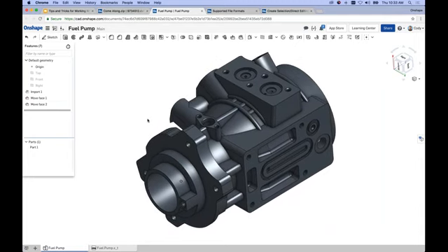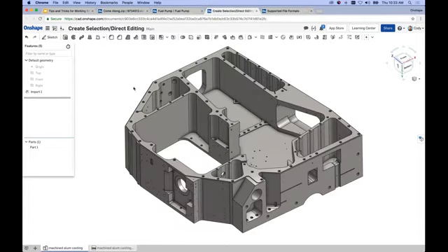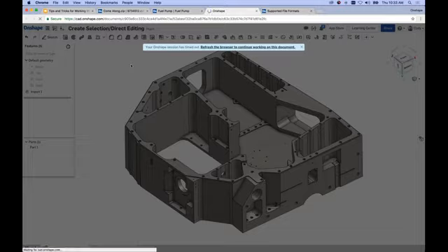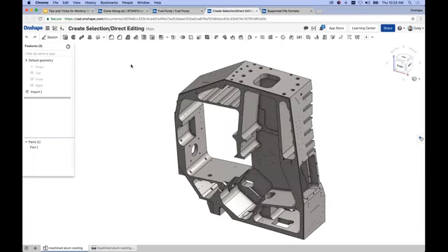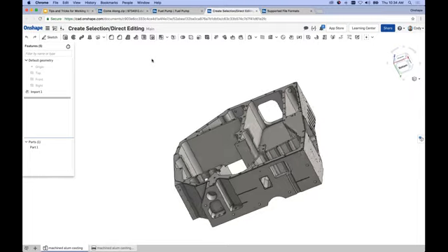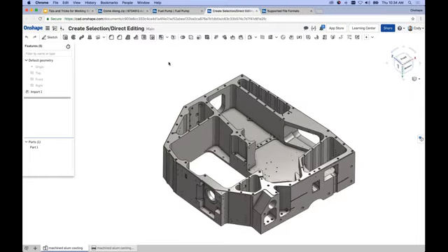So the other move face command that's very powerful is offset. Now I want to jump to just real quickly a different example of this. And I think this is one that's particularly powerful because of create selection. So say, for instance, that you've imported a model and you need to change 50 holes, and you don't want to offset them all at once. Maybe I need to delete a hole or delete a whole bunch of holes, right? Or maybe I need to offset the diameter of 50 holes by 30 thousandths, or 0.1 millimeters or something along those lines.